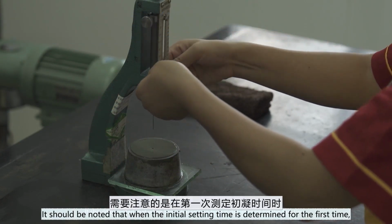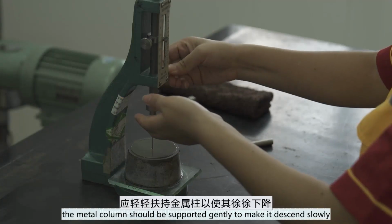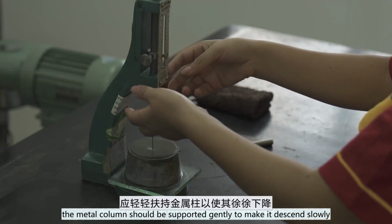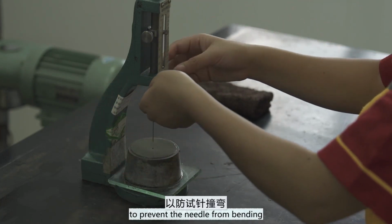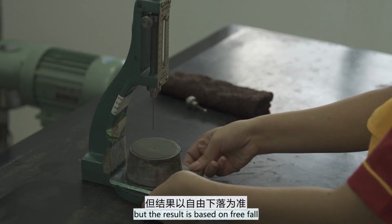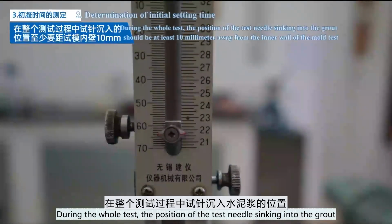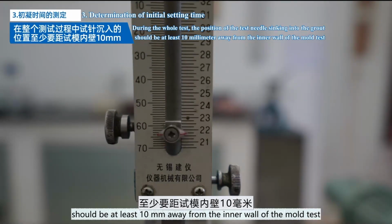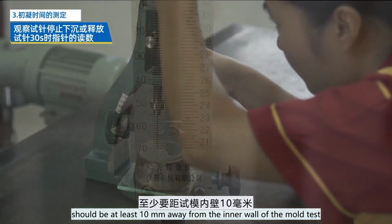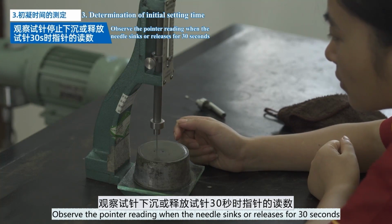It should be noted that when the initial setting time is determined for the first time, the metal column should be supported gently to make it descend slowly, to prevent the needle from bending. But the result is based on free fall. During the whole test, the position of the test needle sinking into the paste should be at least 10 mm away from the inner wall of the mold. Observe the pointer reading when the needle sinks or is released for 30 seconds.